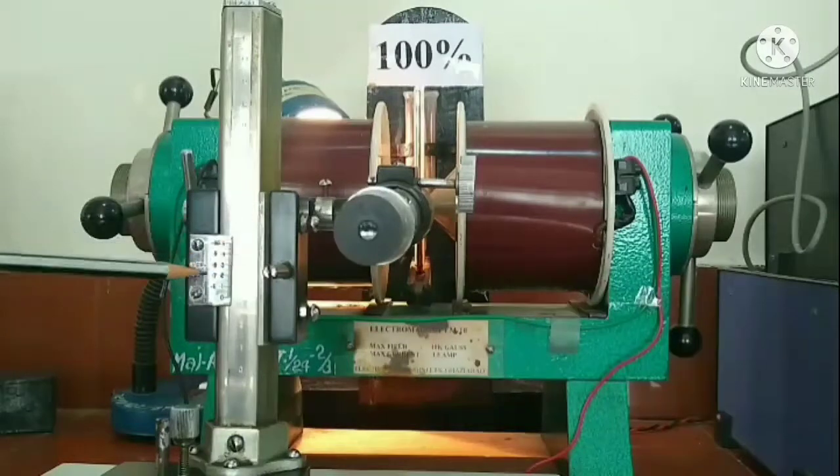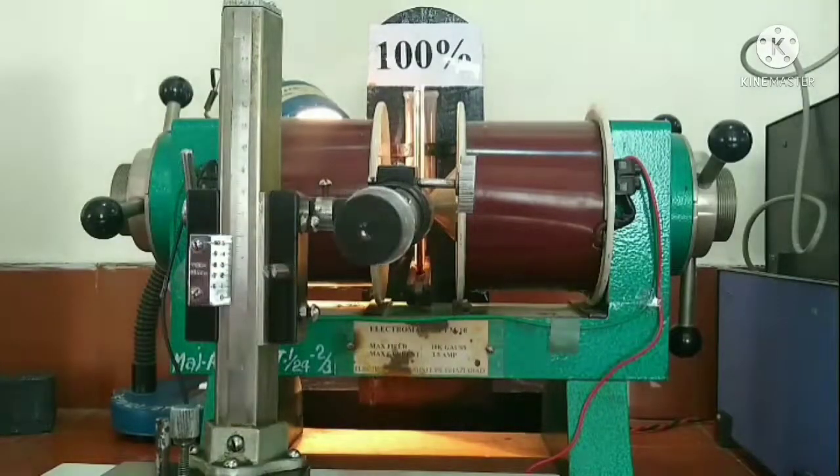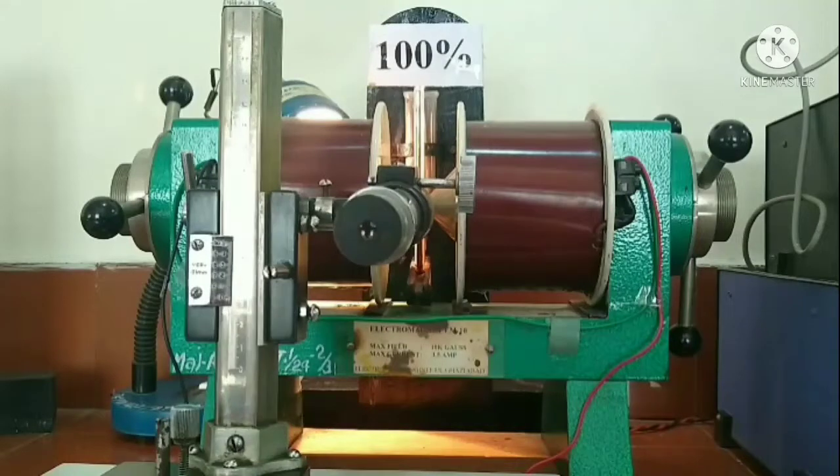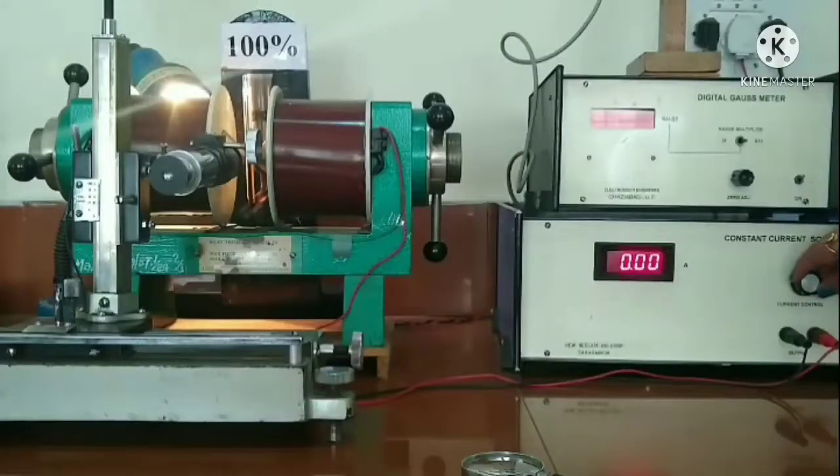So the reading of the main scale would be the division which is in line with the 0 of the vernier or before the 0 of the vernier. So with the help of this lens we can see that 3.2 centimeter is the main scale reading, and the 10th division of the vernier scale is in coincidence with the main scale. So 0.1, because 10 multiplied by the least count would be the reading of the vernier scale. So we'll note down that that will be our initial reading.